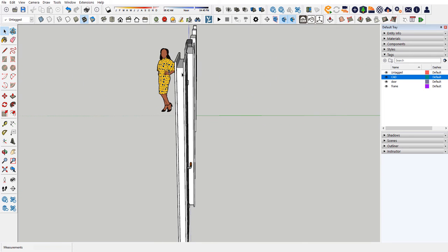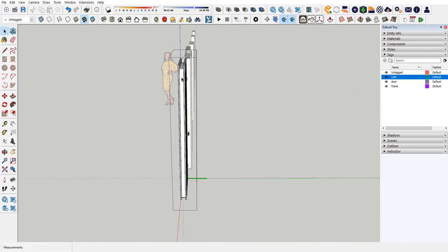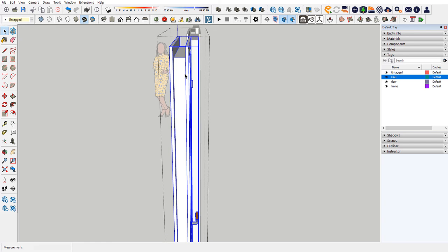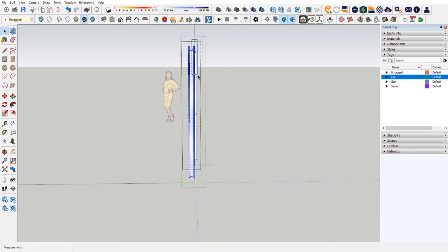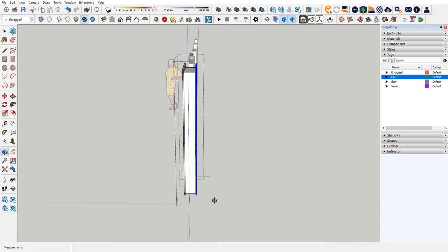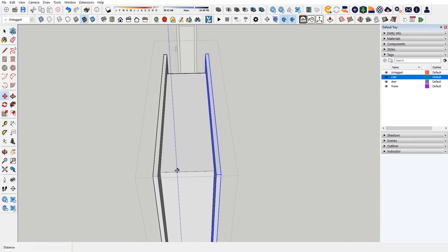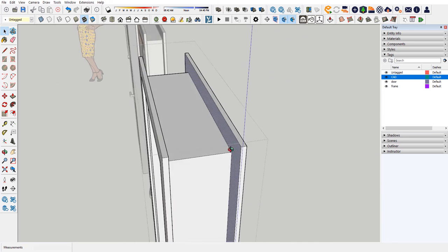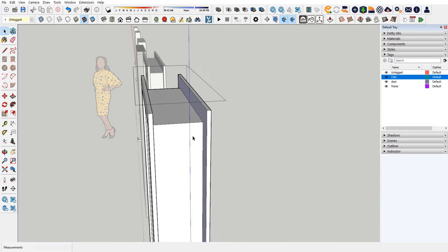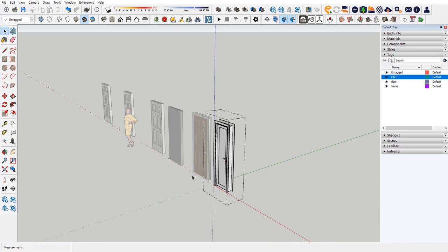If I have to make it deeper for this model, let's say this looks a little thin for wall surfaces. I'm basically going to look like this, grab this frame and make sure I get all of that. Nope, gotta go deeper. There you go. Do a window select because I just want this back frame right here. And I do M for move, and I can make it as thick as the wall I need it to be. Because the inside, the face of the wall goes here to here, right? This sticks out beyond the face of the wall. So I can just put this in and then just stretch that.